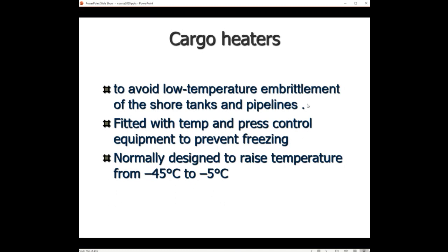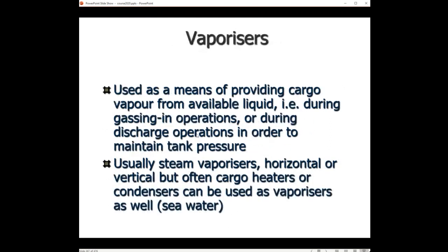So with a cargo heater, we can avoid low temperature embrittlement, damage to the steel of the shore tanks. Fitted with temperature control, pressure control, prevent freezing, yes. And normally we should be able to raise the temperature from -45 to -5, but that is depending on the seawater temperature.